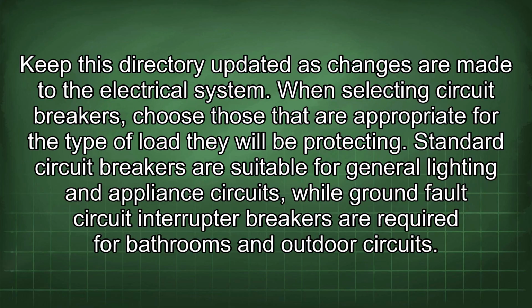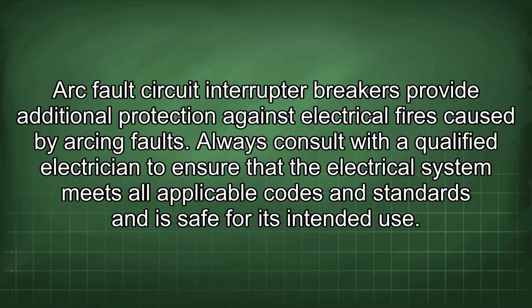Standard circuit breakers are suitable for general lighting and appliance circuits, while ground fault circuit interrupter breakers are required for bathrooms and outdoor circuits. Arc fault circuit interrupter breakers provide additional protection against electrical fires caused by arcing faults. Always consult with a qualified electrician to ensure that the electrical system meets all applicable codes and standards and is safe for its intended use.